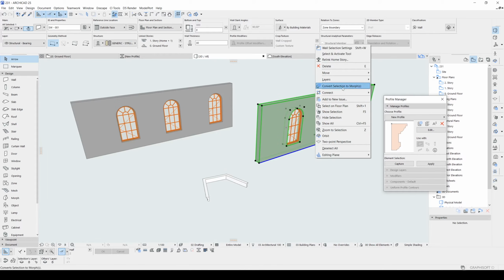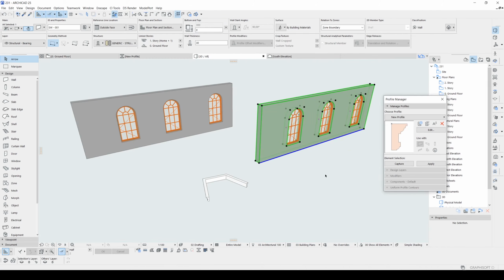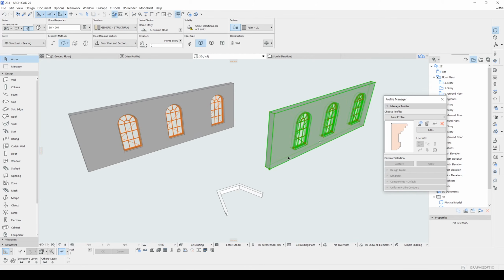Let's right click it and click morph and click OK. After that, we will hit Ctrl plus E and now we will rotate this. Select your pivot point, click here and drag to X direction. Once you achieve it, you will click your Z direction and rotate as horizontal. You can directly input a value here, maybe 90 degrees.